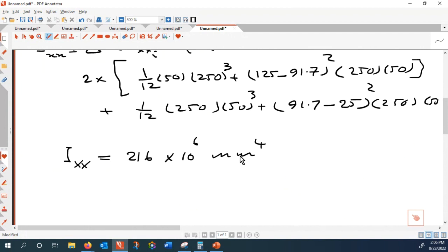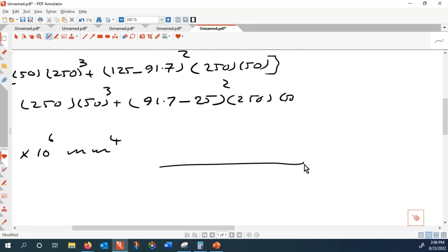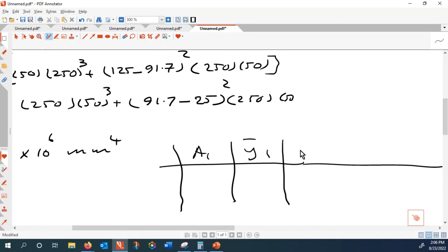But this is, I mean, you just visualize how things are. There is one technique called the tabular technique. The tabular technique is you make a table. This is more suitable for Excel type of calculation. So you make a table, and in this table you have A1, Y bar 1, the product of Y bar, these are I, AI and DI and II.